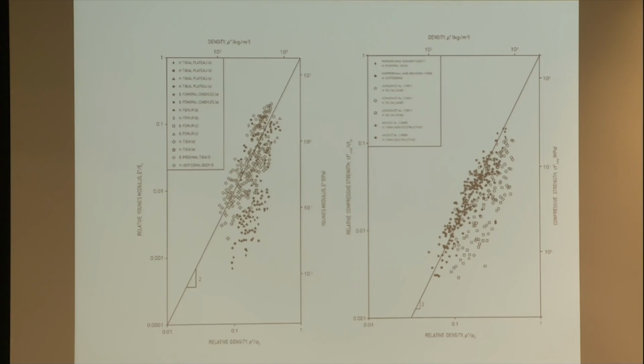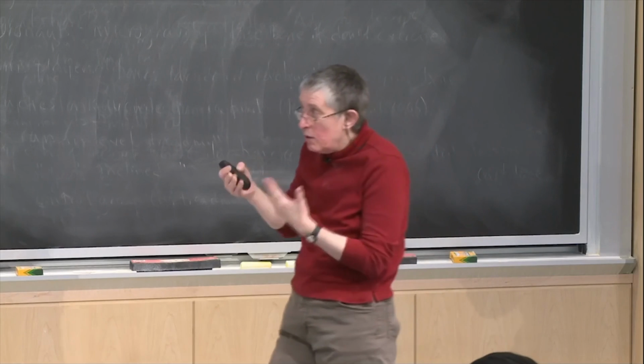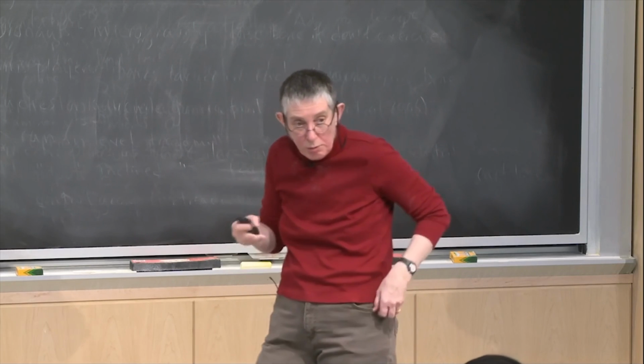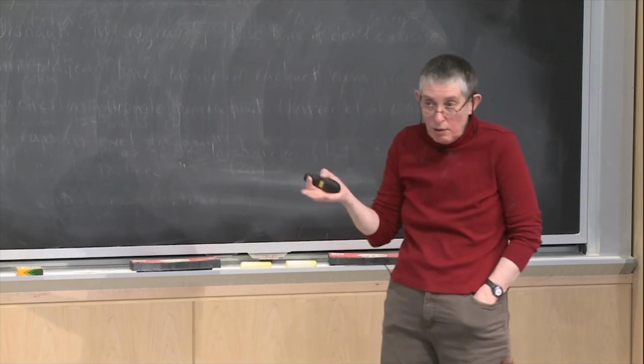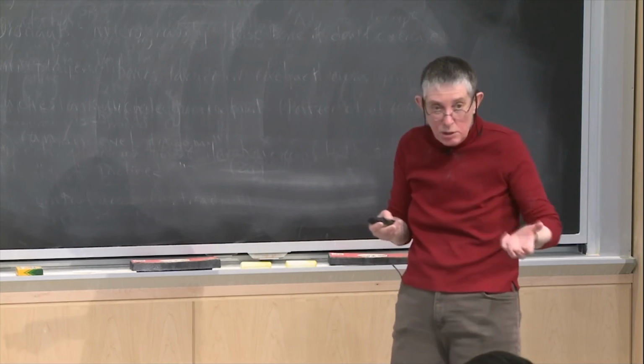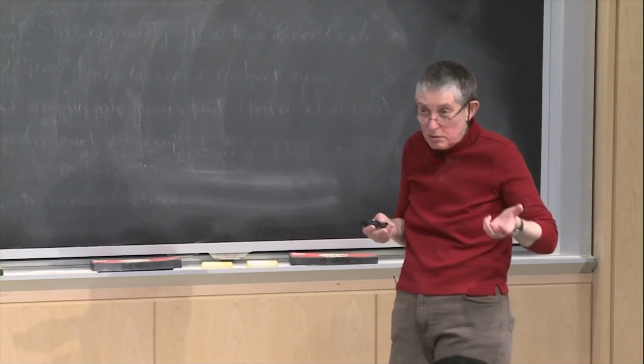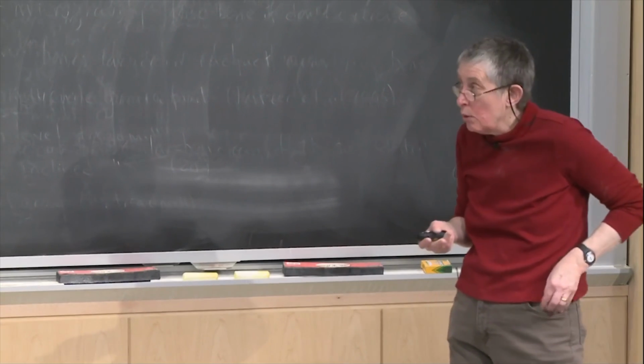And if you think of the open-celled foam model and you had bending of the cell walls, you'd expect the modulus to vary as the density squared. So that's the limit of how we do the modeling. We're really just interested in seeing how the properties vary with density. If you had a particular piece of bone, I don't think you could use the models to exactly predict the modulus of that bone.